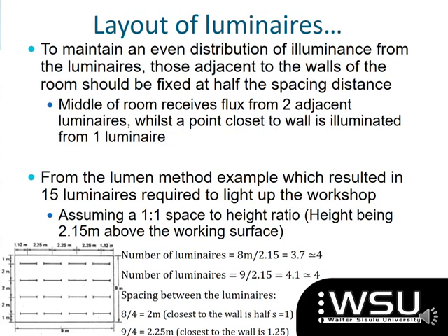So therefore I plug in 1, 2, 3, 4 luminaires, and I show your 2 inner luminaires being 2 meters apart, and I put the other 2 luminaires 1 meter from each side of the wall. So you can see the side with the 8 meters: from the wall to 1 meter a luminaire, then 2 meters away another luminaire, another 2 meters another luminaire, another 2 meters another luminaire, and that last luminaire is a meter away from my wall. And you can see there it's 4 luminaires.